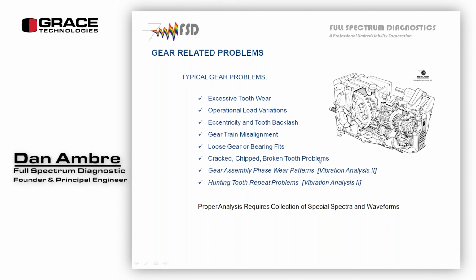Cracked, chipped, and broken tooth problems. These are rarely seen in the spectrum. They show up in the time waveform. And in the time waveform, it'll look like a pulse every revolution of the gear. And we'll talk about that in a sec.